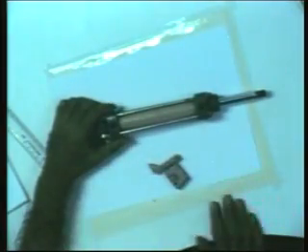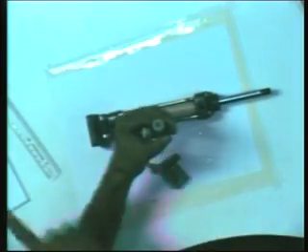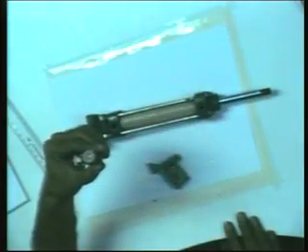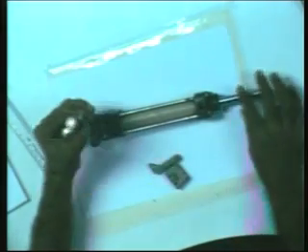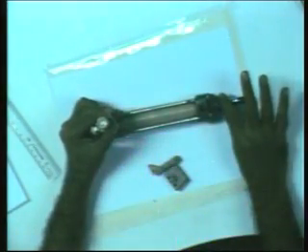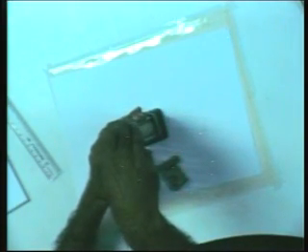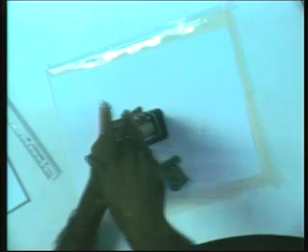A hydraulic cylinder is similar, except that instead of air, I pump in oil. I pump oil through a valve, typically something like this. Oil comes in, goes out into the cylinder. The cylinder will be more or less the same. Now, in the case of a hydraulic cylinder, I can control the motion of this. When I shut the valve, it will stop where it is. And if there is a load and there is oil below, oil is incompressible. It won't move, unlike in pneumatic.